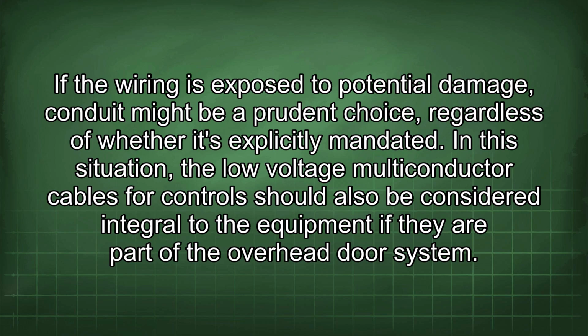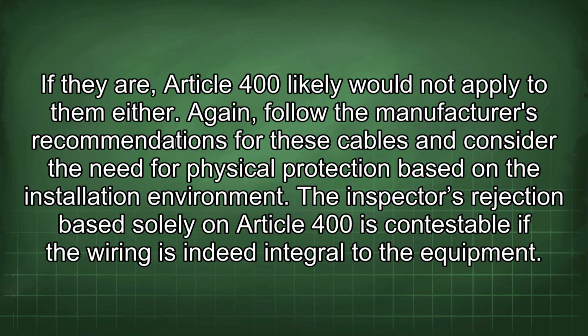In this situation, the low-voltage multi-conductor cables for control should also be considered integral to the equipment if they are part of the overhead door system. If they are, Article 400 likely would not apply to them either. Again, follow the manufacturer's recommendations for these cables and consider the need for physical protection based on the installation environment. The inspector's rejection based solely on Article 400 is contestable if the wiring is indeed integral to the equipment.